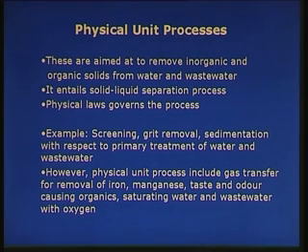Whenever the volatile organics are present in water and wastewater, by supplying the oxygen, by forcing the oxygen with turbulence into the water and wastewater, we can drive out the taste and odor causing organics.